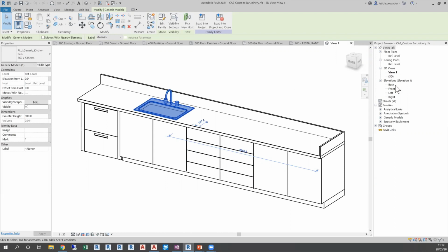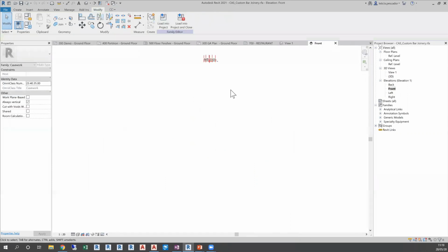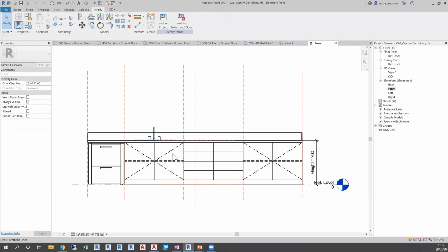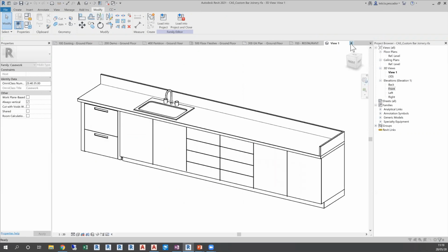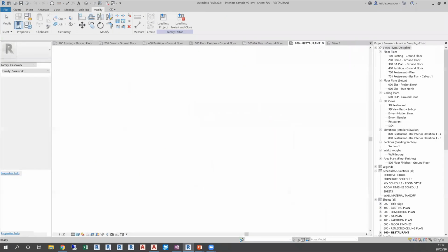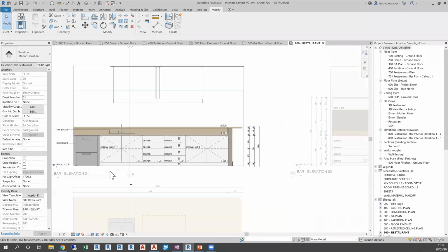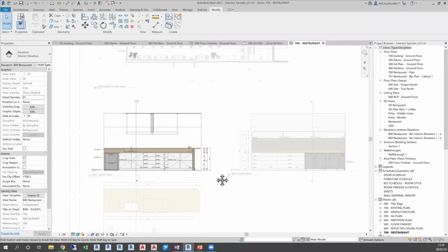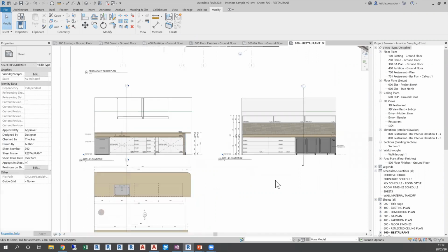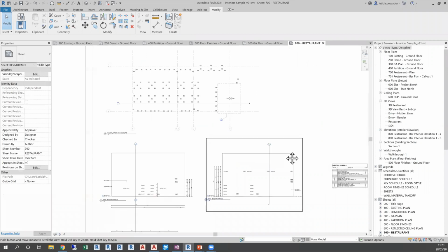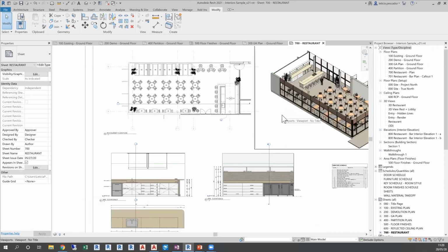This family will have pretty much elevations that are also created within those views. So you can create line work to represent shelves, etc. And you can also create very fancy components if that's required. So from here, anything and any update that I did will get automatically changed. So that drawer that I have updated got automatically updated within that floor plan as well.